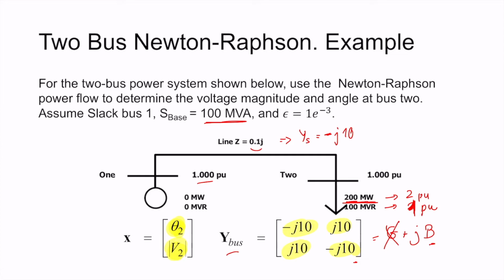Actually, this has a name. This is the straightforward initialization or guess that I can give to these initial variables. For the magnitudes of the voltage, giving the value of 1. For the deltas, or sometimes I call them thetas, giving the value 0. This is called flat start.